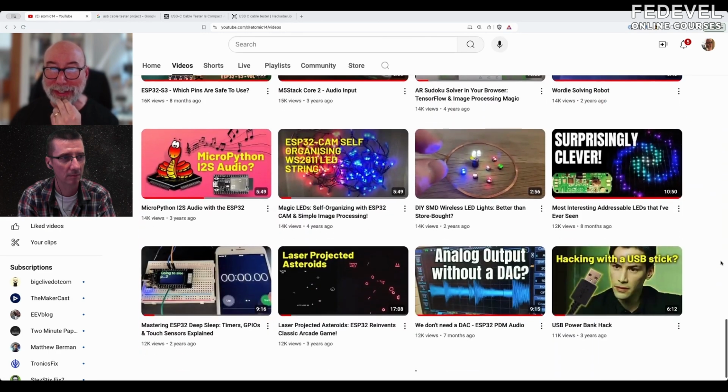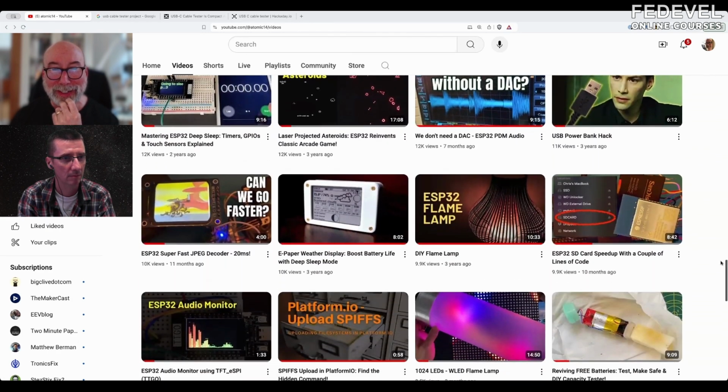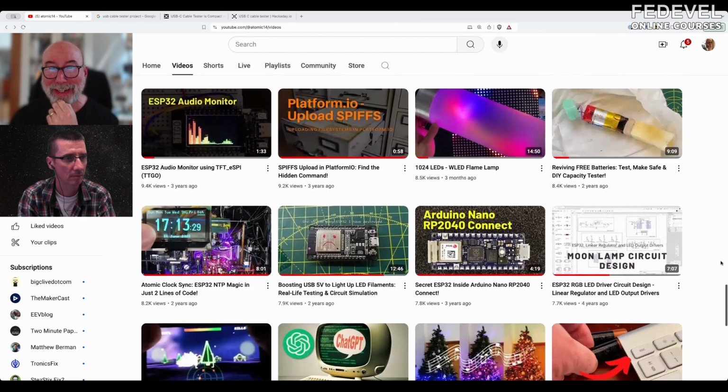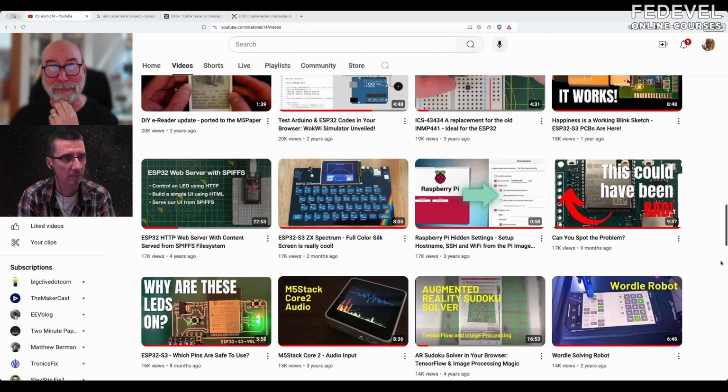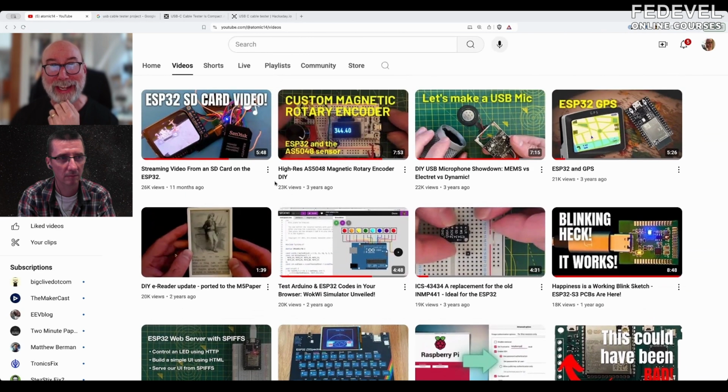So I ended up with an ESP32 connected to the SD card, and a mass storage controller with a USB interface connected to the SD card, and then some crazy way of toggling between the two. I would disable the ESP32's USB, so this mass storage controller could take over the USB, talk to the SD card, and upload files really quickly.